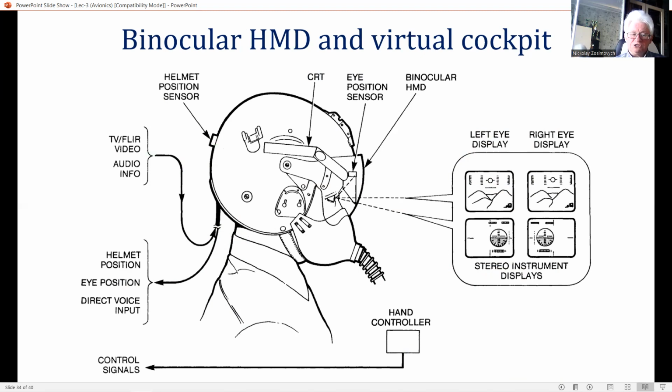or a virtual instrument panel display. Carried to its logical conclusion, the normal head-down displays and instruments would no longer be required. Simple standby instruments of the get-you-home type would be sufficient to cover the case of a failure in the HMD system. Such a bold step, however, is still several years away from implementation in a production aircraft.